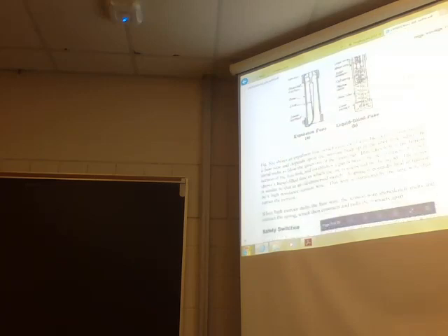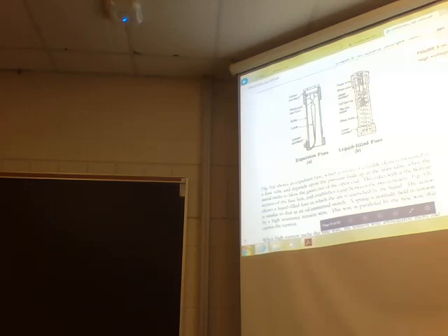Similar to these would be what you would see on a utility pole. The fuse holder is a C-shaped bracket with the conductor on each end of it. The fuse would go in the middle, making it look like a D shape as opposed to a C when the fuse is in there and working. When the fuse blows, there's a hinge on the bottom of the fuse holder. When the fuse blows, it drops out, and you can visually see that the fuse holder is open, so the fuse has blown.